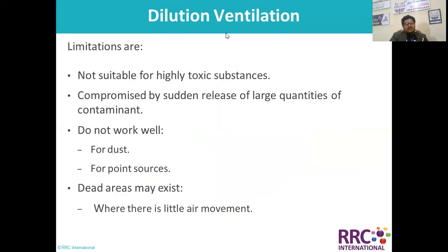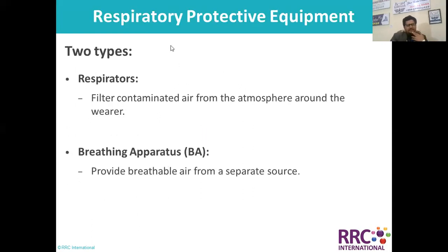But of course, there are limitations for dilution ventilation: it is not suitable for highly toxic substances, it is compromised by the release of large quantities of contaminants, and it does not work well for dust and for point sources. Like in our Saudi Arabia, dilution ventilation wouldn't be so effective. Dead areas may exist where there is little air movement. And why is it not successful in Saudi Arabia? Because of sandstorms, high wind speeds, and several other reasons.